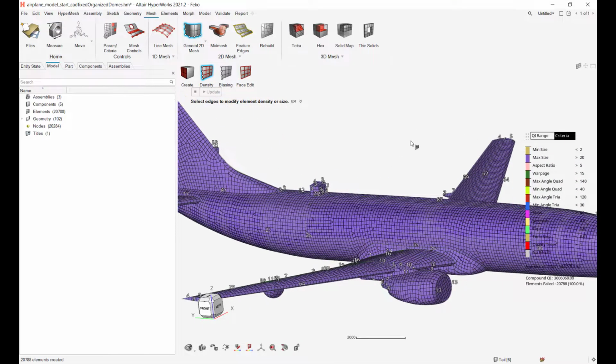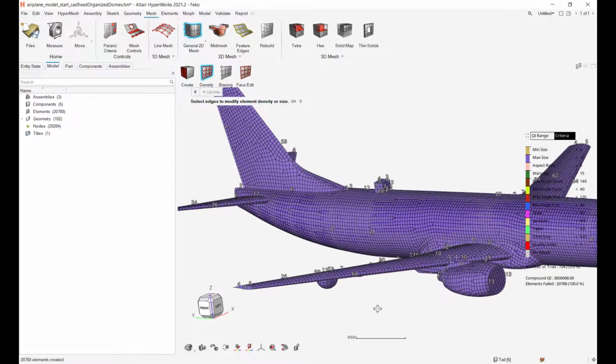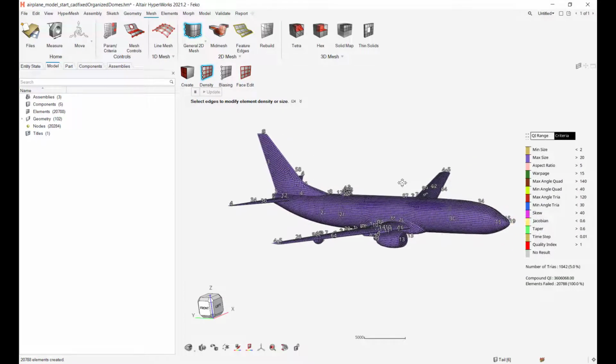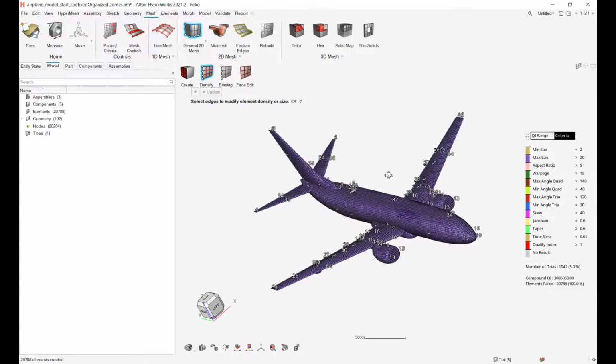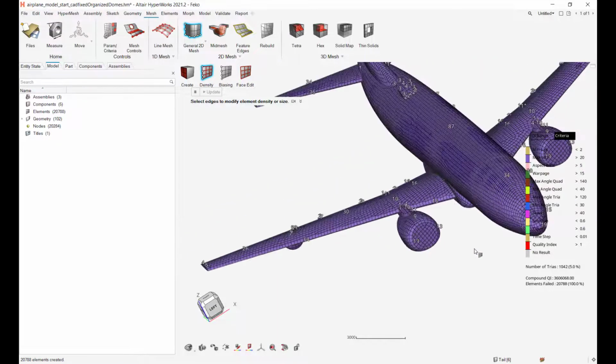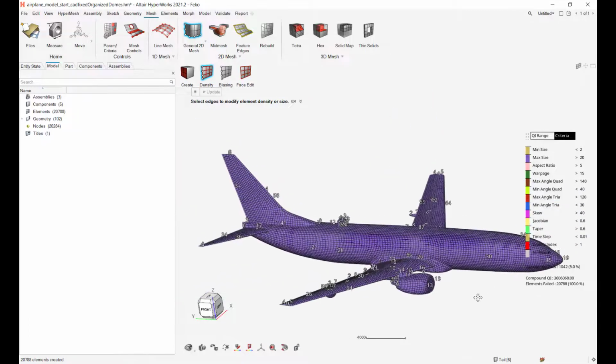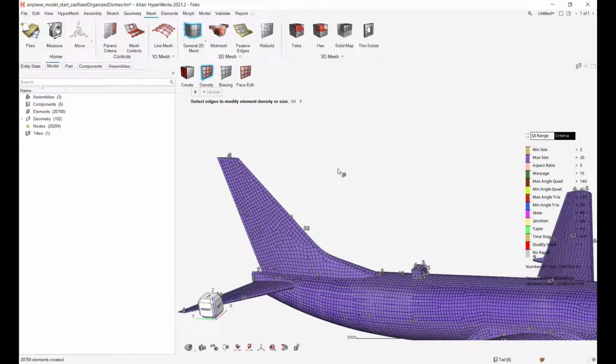Okay. So understanding for FEKO that everything is more of an STL mesh. Even if you're not using this for FEKO and you're using this for a different electromagnetics tool, most things are STL as far as I have understood. So this is not the greatest mesh in the world for you, but just kind of looking at it, it's not bad, right? These circles look pretty good. The flow is pretty nice. There's certainly triangles that we can get rid of, and you can make an argument for why are they there, etc., etc. But these are the default options.